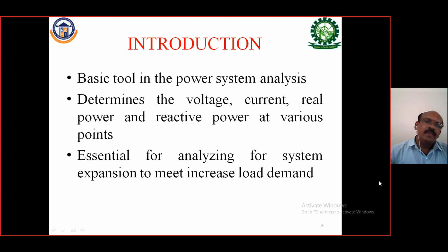Okay, introduction. The basic tool in power system analysis: we know the basic laws, Kirchhoff's voltage law and current law. In power system problems, we are using Kirchhoff's current law. We apply it at all the buses, and also we find out the voltage, current, real and reactive power flows in the power system.